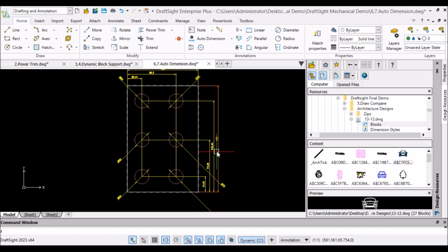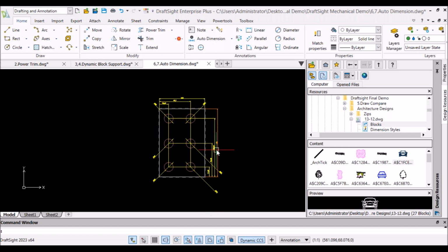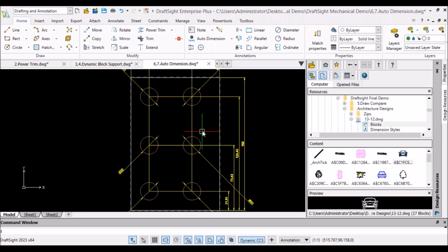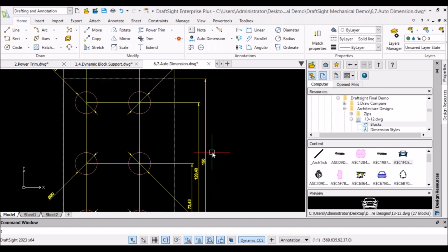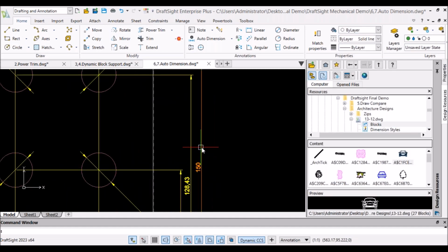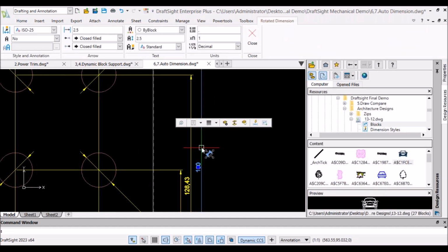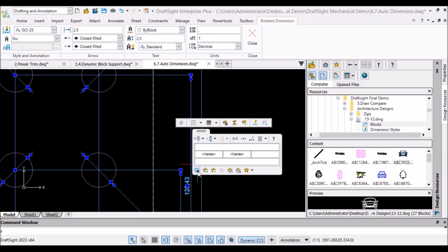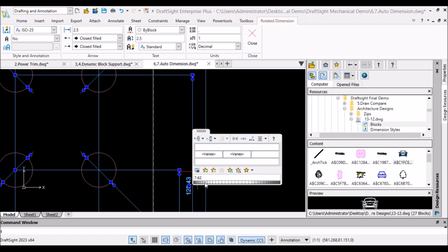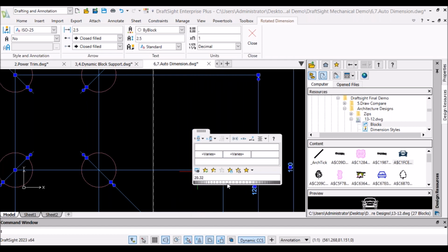So you want to sort that dimension and you want to give some spacing in between that. For that we have this auto arrange dimension tool. To execute that, select any one of the dimension, press Control A on your keyboard. Just go to this dimension palette symbol and click twice over there and just simply drag the scaling factor and increase scaling factor as per your requirement.